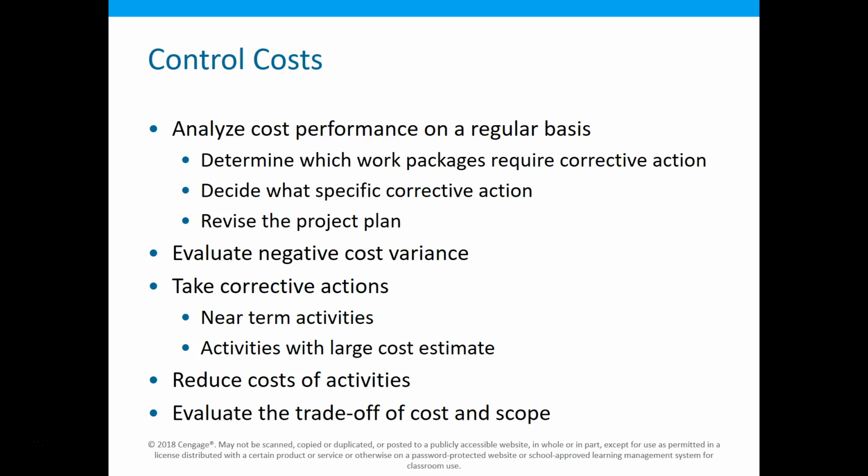Well, originally we were going to have a 6-foot shoulder on this road. Kansas Department of Transportation, can we do a 5-foot shoulder and get us back on track? So sometimes we can renegotiate. Those negative cost variances over time are what's going to put our project behind schedule and budget. And so we need to be looking at those cost drivers. What is our cost? Why are we higher?